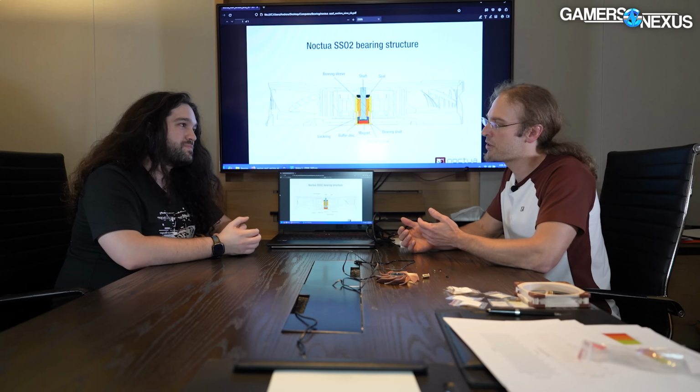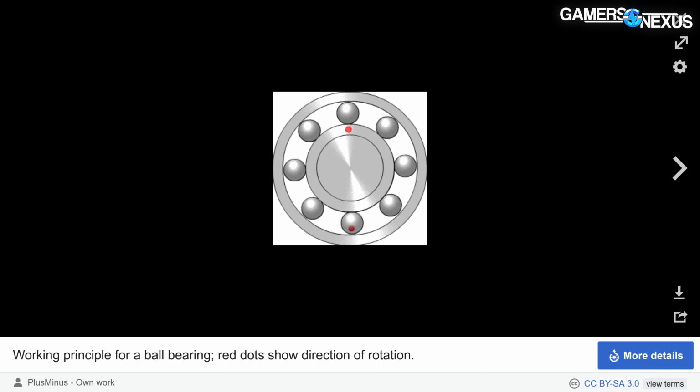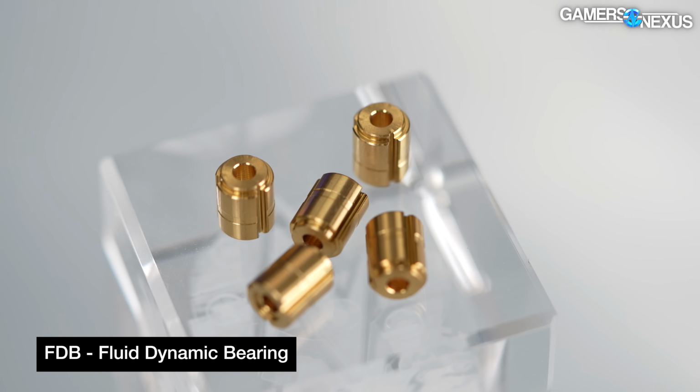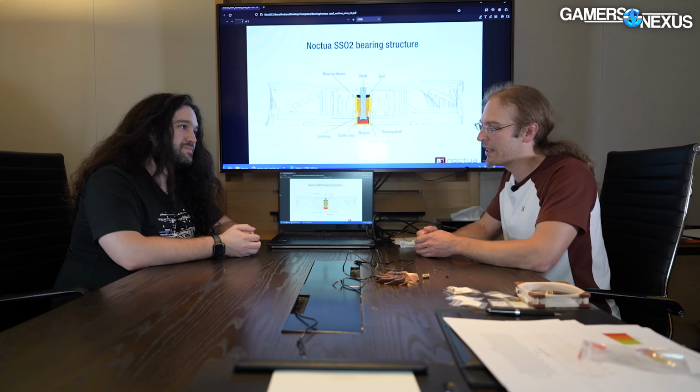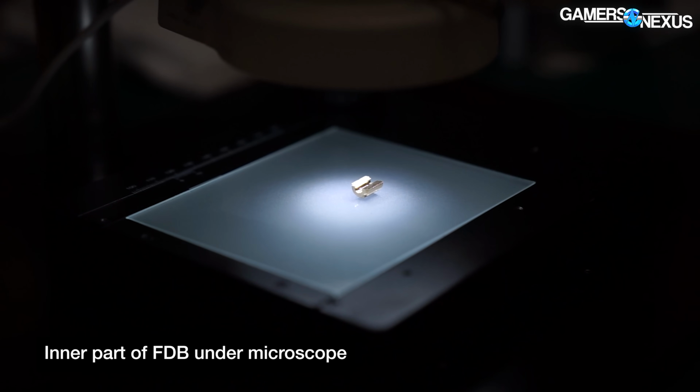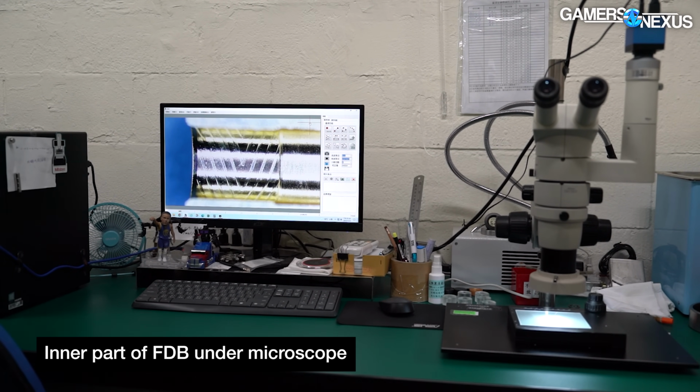From a technical perspective, it's easy to distinguish ball bearings and sleeve bearings. That's a very straightforward distinction no one can really argue with. But what actually makes an FDB or HDB bearing is not as straightforward. A lot of people have those herringbone grooved bearings in mind, so it could either be the shaft having a herringbone or spiral groove inside, or the bearing sleeve. But the name fluid dynamic bearing as such only says that there is a dynamic pressure field on the fluid. And that's exactly what happens with any lubricated sleeve bearing as well.